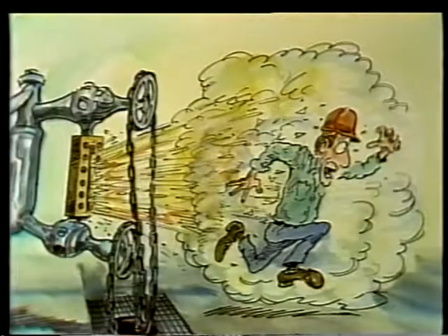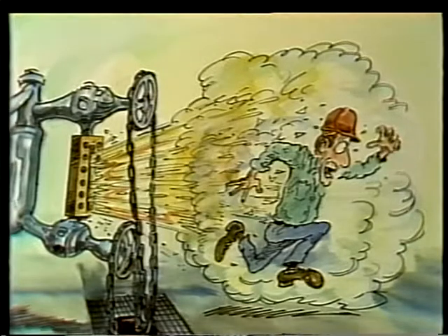The final problem, complete failure of the gauge glass, occurs when the glass is blown out of the gauge. Besides being a malfunction of the gauge glass, this can be a safety hazard, especially if the valves don't have ball checks. In a high-pressure boiler, this kind of failure releases high-temperature, high-pressure water into the plant, which is dangerous to plant personnel.